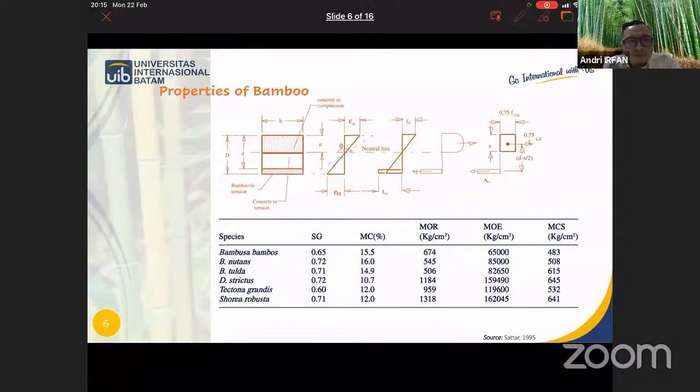Also, the variation of fiber volume fraction across the thickness of bamboo at the three parts is given in the slide. It is observed that the fiber distribution is more uniform at the bottom than at the top and the middle parts. It means bottom, middle, and top have similar thickness and the same strength. However, the difference between the distributions is not very significant. Yeah, it's unique to bamboo strengths.